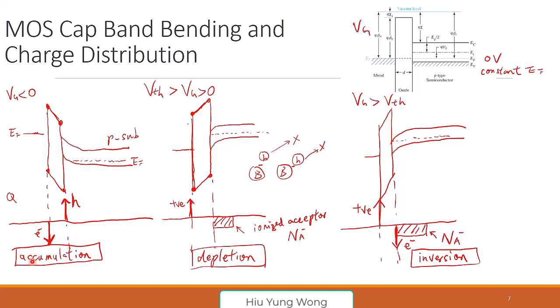This is called accumulation. Well, it accumulates the holes. This is called depletion. Depletion of holes and electrons. And this is called inversion. What does it mean? So you start with the P-type, I guess, and now since the Fermi level is above the conduction band, it's like n-type, so inverted. Excellent. Exactly. Because we start with the p-type, now with a lot of holes, with high enough electric field, it becomes n-type at the top, right? N-type in the sense that it has more electrons. So we say it is inverted, okay?